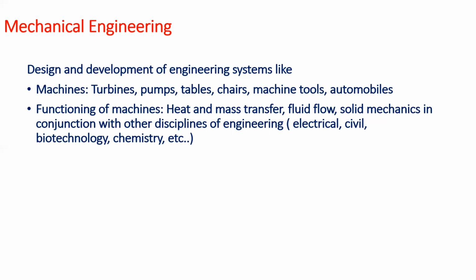One, the wire needs to conduct electricity. Second, due to the motion of electrons in the wire, it gets heated up due to Joule's heating effect. And the electrical insulation coating, whichever is being laid on the wire, also has now two purposes. One is it must exhibit its electrical insulating characteristics. And the second thing is it must also not let the heat dissipate to the surroundings. So it has to be both electrically insulating as well as thermally insulating.